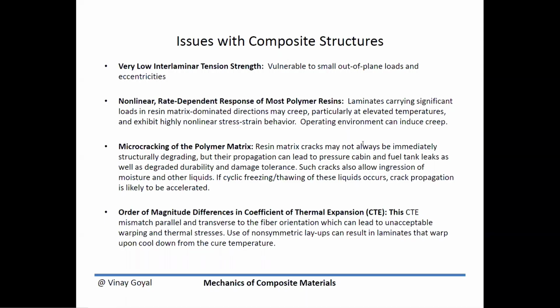Another consideration to keep in mind is that when you're manufacturing composites, depending upon the stacking sequence, since there's a mismatch in the CTE parallel and transverse to the fiber directions, you can introduce unacceptable warping and thermal stresses, especially if you use non-symmetric layups.